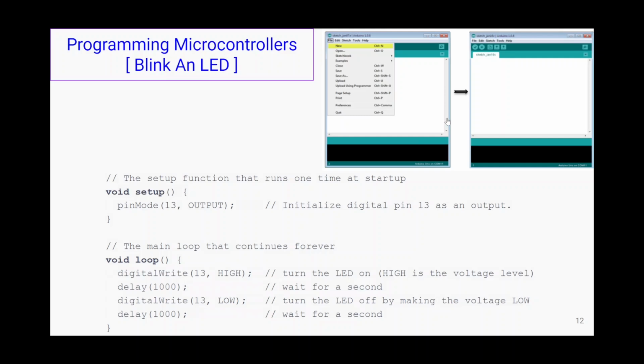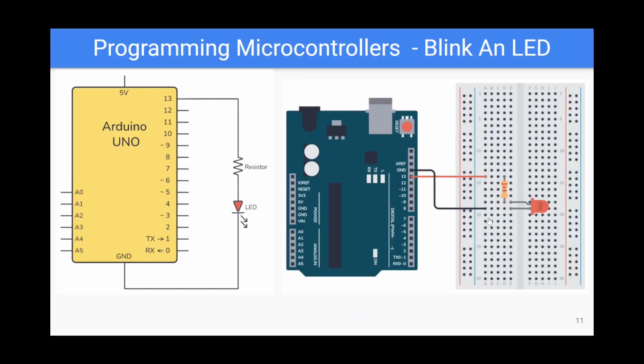Because what's going to happen, let's go back here. So when this pin becomes high, high means it's positive voltage or plus, let's assume that's plus 5 volts. So there will be a current flow from plus 5 to the ground, and because of that the LED will glow.